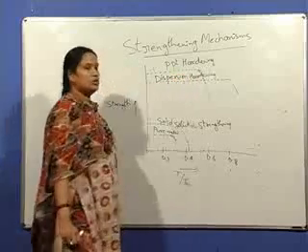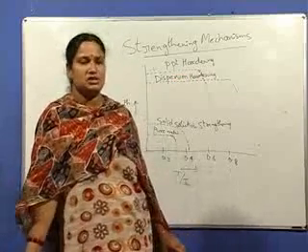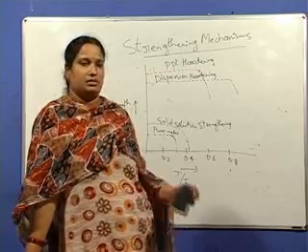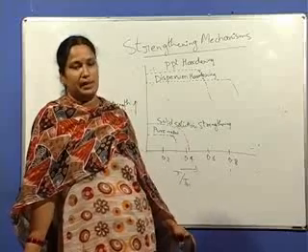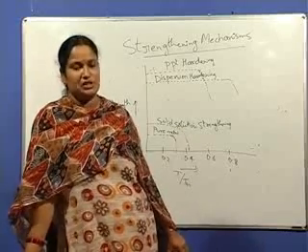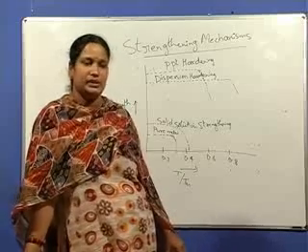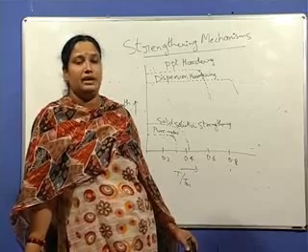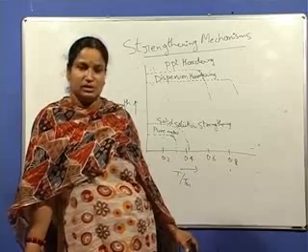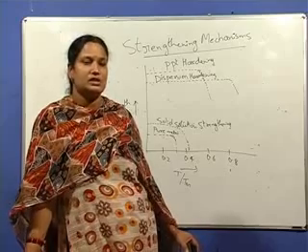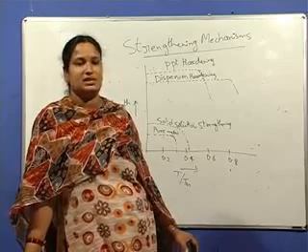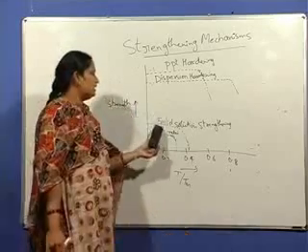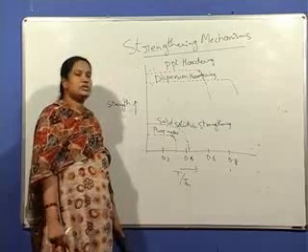Among all the strengthening mechanisms, precipitation strengthening has the highest strength. Next is dispersion strengthening. It is lower than precipitation strengthening, but at higher temperatures it retains its strength. The main reason is that the dispersoids coarsen to a lesser extent compared to the precipitates, which coarsen very rapidly at higher temperatures. The least is the solid solution strengthening.